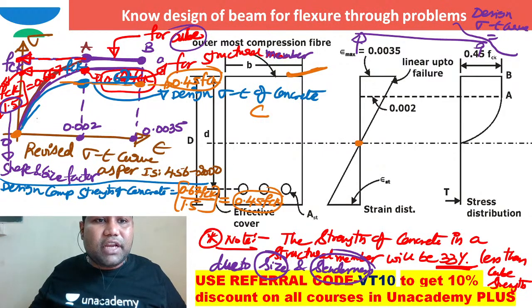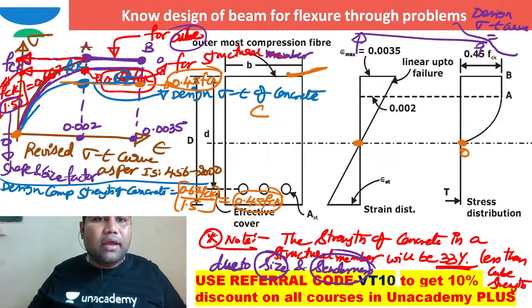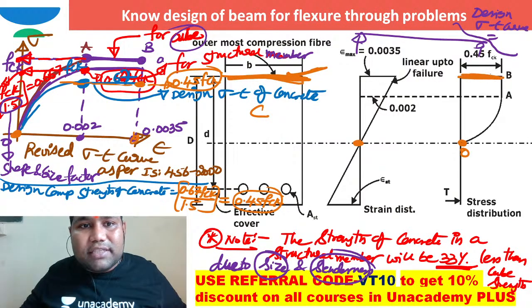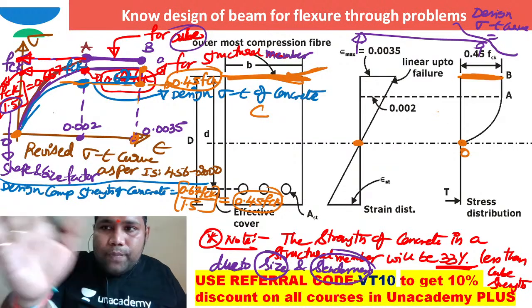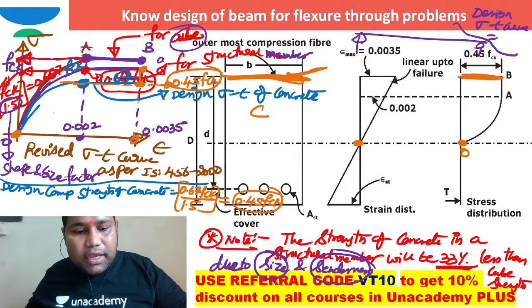So the same stress block, I can reverse it. I can keep the same thing here. There is zero strain, so this point O can come here. Maximum strain is possible at the extreme compression fiber here. So here I can say maximum stress is possible, and the maximum stress is the same stress strain curve. Try to keep it here in this way.